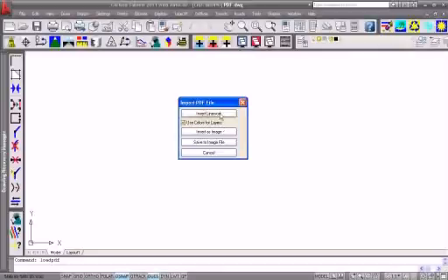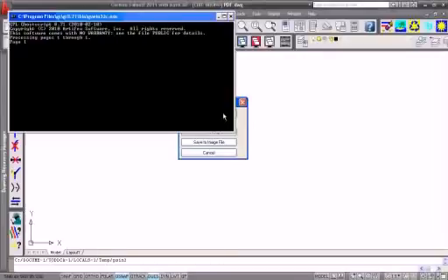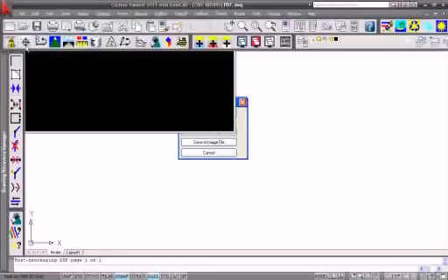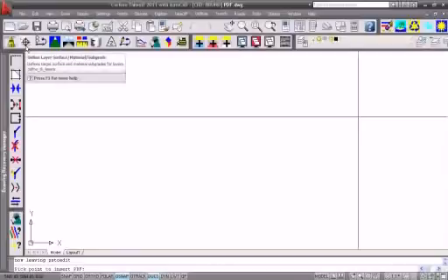So I'm going to say Insert Line Work. Okay, and something else that's new is you see it's saying processing pages 1 through 1, page 1. Before we had a limit of only working with a PDF that had 1 page. Now if your PDF has 20 pages, you can select which page you want to process and which ones to ignore. And it can process multiple PDFs, and it will just stack them in your drawing. Instead of before, what you'd have to do is open up that PDF and save out a page to bring it in. So we now handle multiple pages on the PDF.